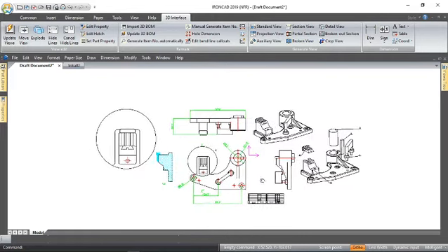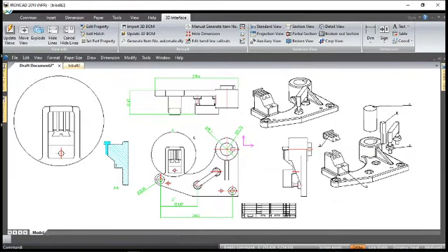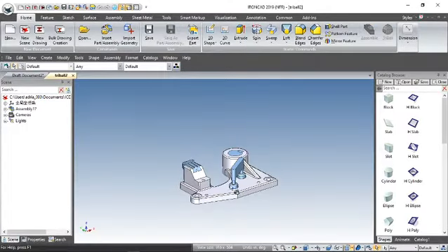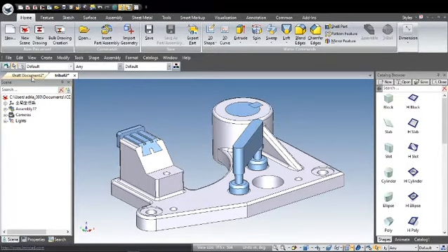can see that you can very quickly create very intricate sort of or detailed drawings from the model in double quick time. That takes literally a minute or two, and you've got your 2D drawing. The nice thing about that is that if you actually go back to your model in here, and maybe what I'll do, I'll just come in here, and if I drag a hole onto here like so, going down through the part, and go back to the actual drawing.